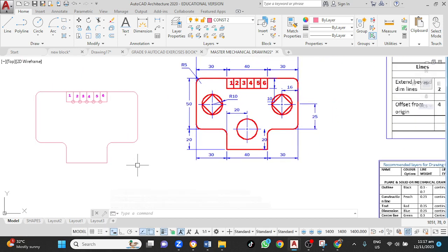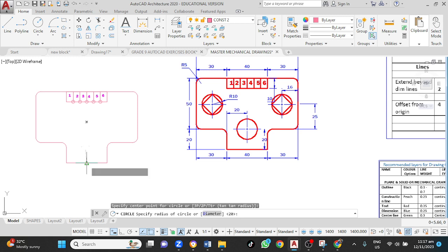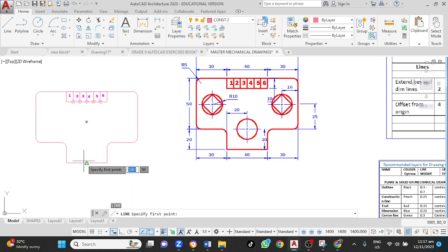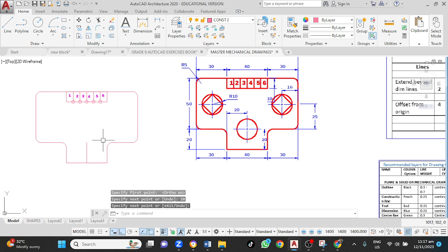The next step is to establish the center for this. This seems to be right in the middle of this one right here. So I could use a circle or a line, left click here, up. Let me use a line. Well, circle works as well. Line, enter. Turn on auto mode. Up 20, 2, 0, enter, enter. That is done.